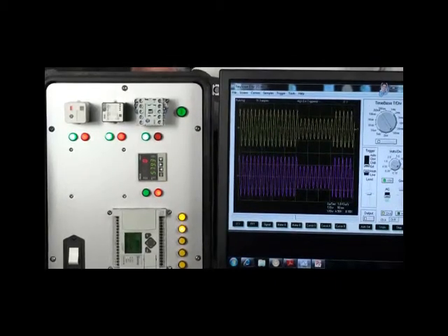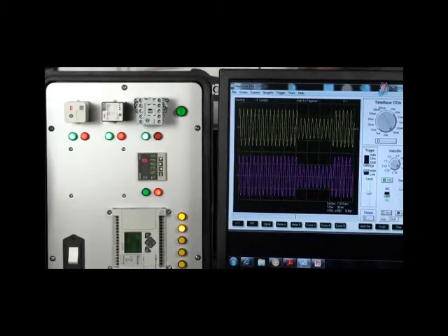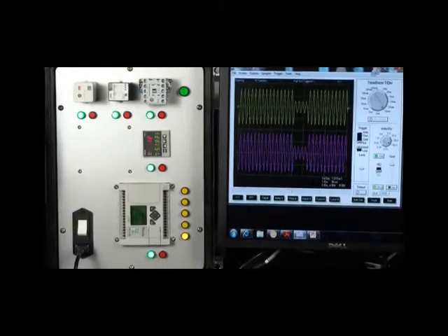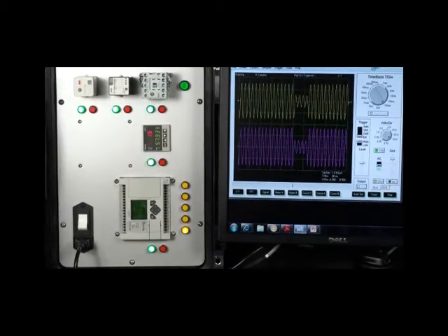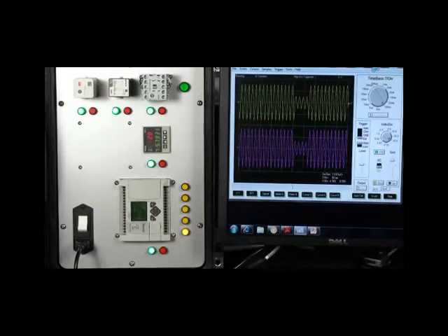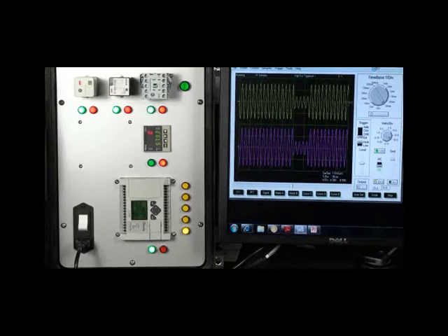And of course your PLC program, since it's running, is likely going to stop the line and say, wait, reorient, get things back in sync. Okay? So let's do another one. On February 26th of this year, at about 9 a.m., we had a voltage sag in the Milwaukee area that dropped to 37% remaining, and it lasted about 70 milliseconds. So I've set my system up for that. We're going to generate that sag and see the effect.